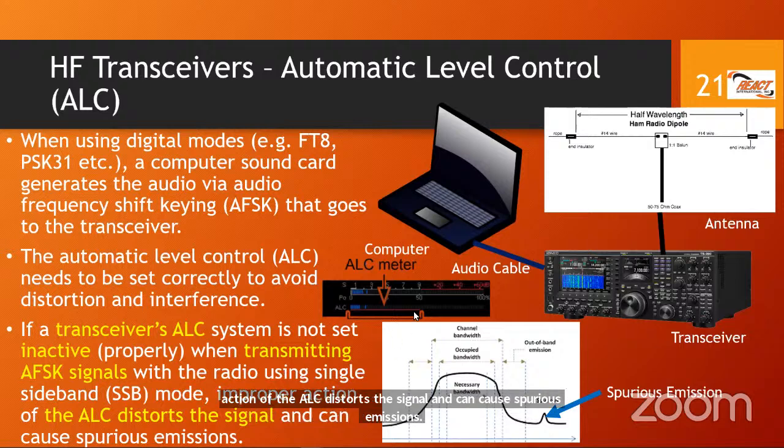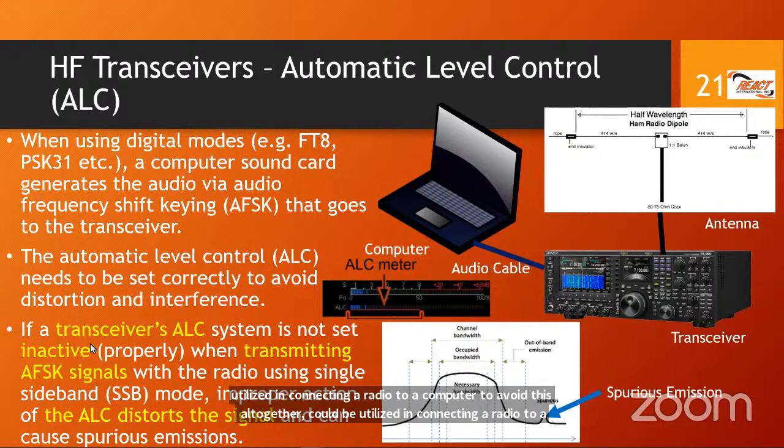Of course, there are other features that could be utilized in connecting a radio to a computer to avoid this altogether. But for exam purposes, you need to know that if the transceiver's ALC is not set inactive, meaning it's not switched off, or it is set improperly, when you transmit AFSK signals for digital modes using SSB, improper action of the ALC distorts the signal, and it can also cause spurious emissions. But ALC distorts the signal is the point for the exam question.